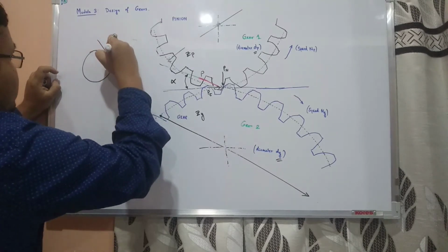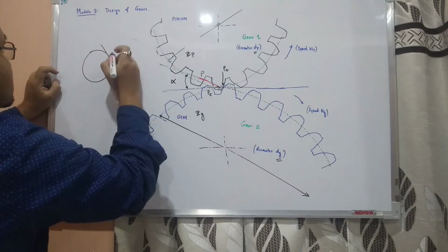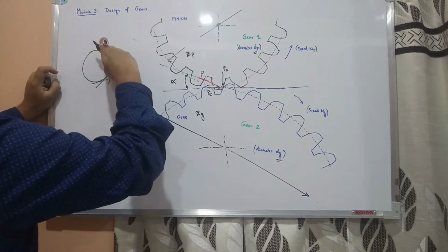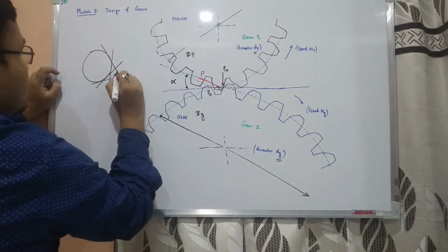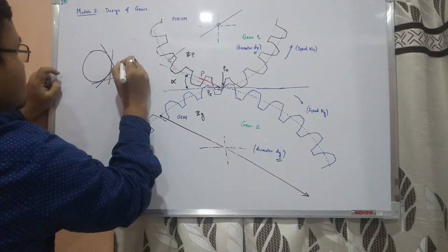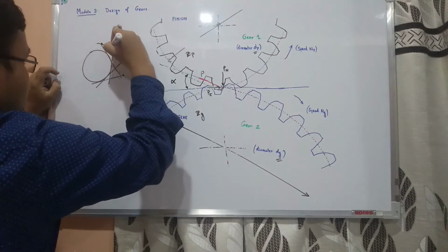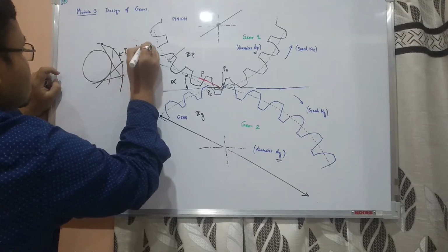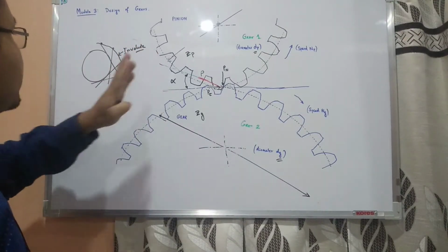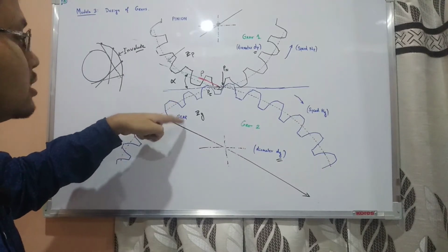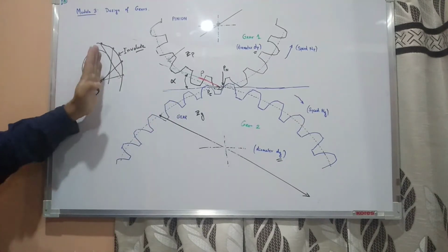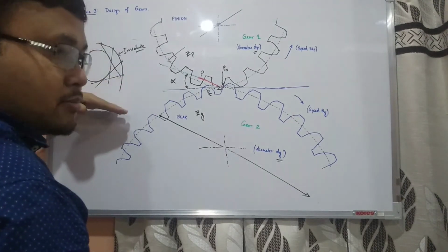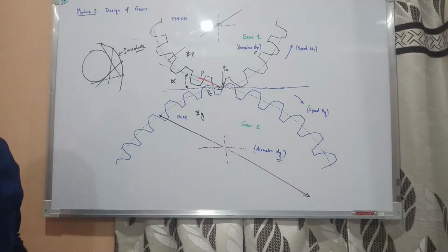So this is the first position, then the second position will be here, third position is there, fourth position is there. This line is rolling like this, and its end will draw this. If we connect all the points, its locus is the involute. Now see, why do we make this part an involute? Because involute is something which is obtained by purely rolling something over a surface, right?